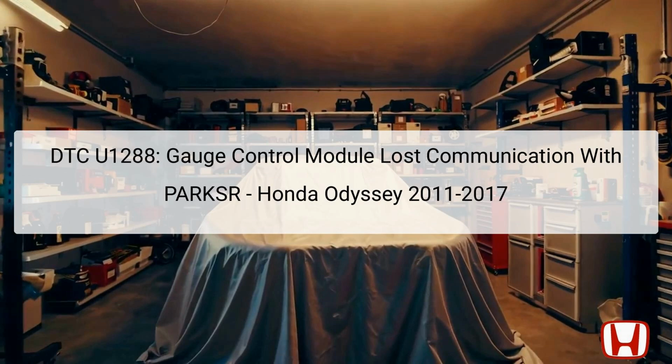The gauge control module is responsible for relaying information regarding vehicle data to the dashboard displays, while the parking sensor module detects objects behind the vehicle. Both components are integral to ensuring that the driver receives correct information when reversing. When the communication link between these two modules is compromised, it can lead to a cascade of malfunctions, affecting vehicle performance and safety. Understanding this error is vital for appropriate diagnostics and repair to ensure operational reliability.